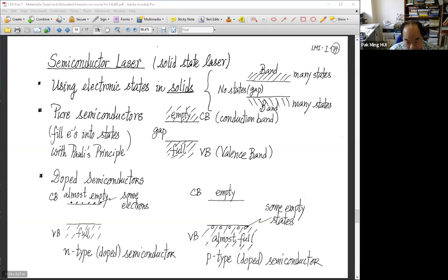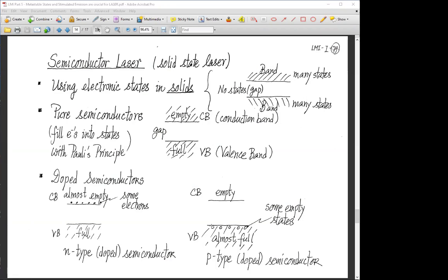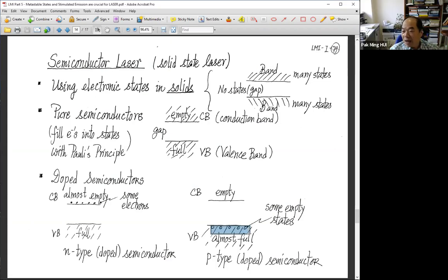In this way, boron can take some electrons out from this otherwise full valence band. I represent it by some empty circle here. Those are the empty, not occupied electron states, okay? So boron has this ability, take something out of the band, okay? And that is called p-doping.